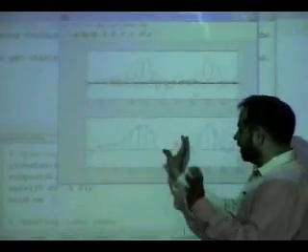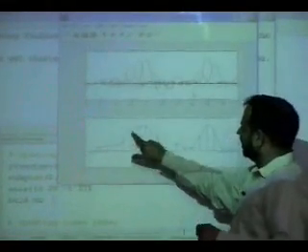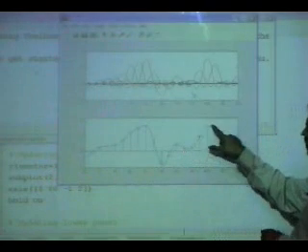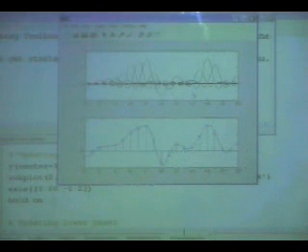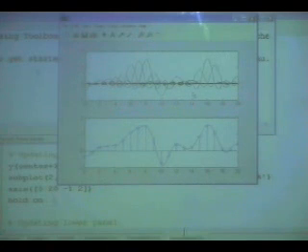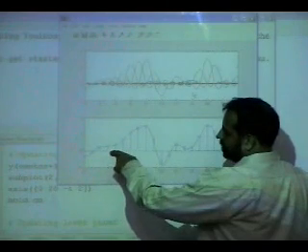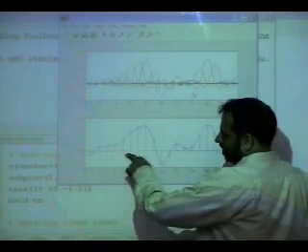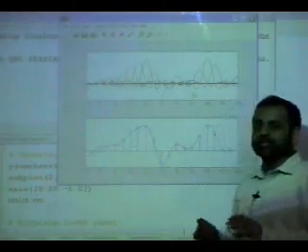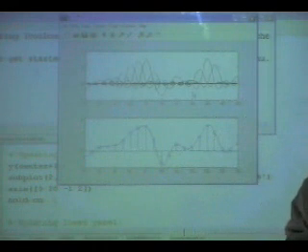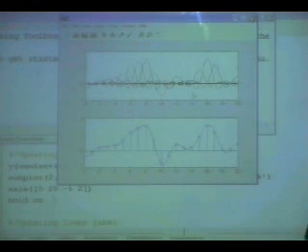So now the blue signal is no more there. What you have is the signal. Right, so this is the reconstruction process. In the reconstruction process, all you have to do is at every sample location copy a sinc, and the sinc must pass through zeros at the location of other samples, so that it should not corrupt the value which you already have.